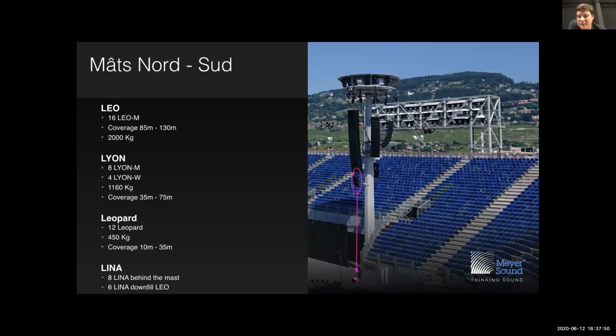And so this area here is on a separate feed, so they receive the same feed as the PA, but we can influence that when we have a choir sitting down. We can reduce the gain, we can reduce volume in here, because people here will get the direct sound, and we will get more gain before feedback. So I'm going to follow with the predictions.